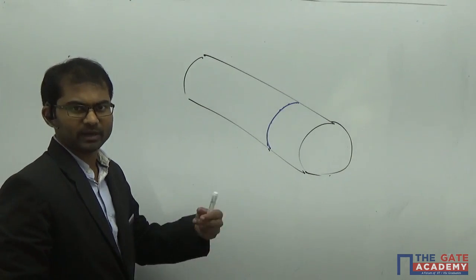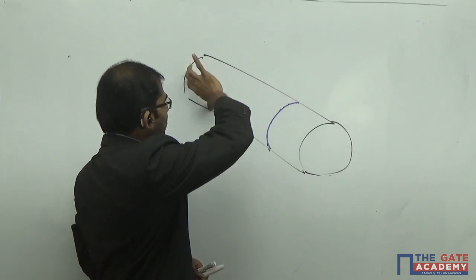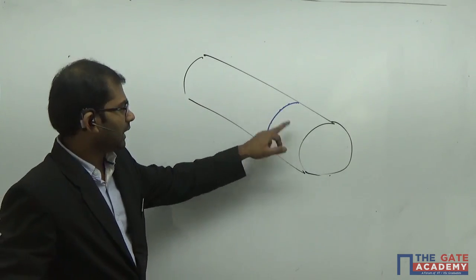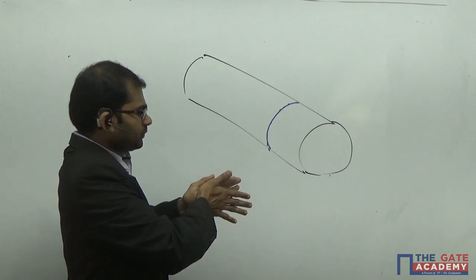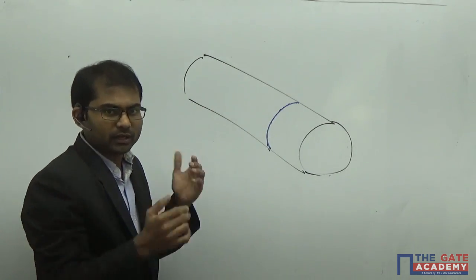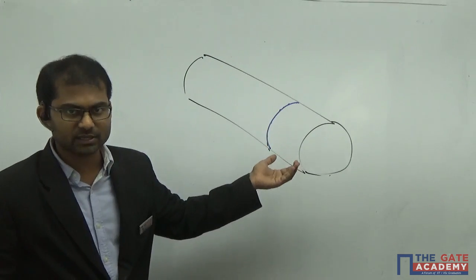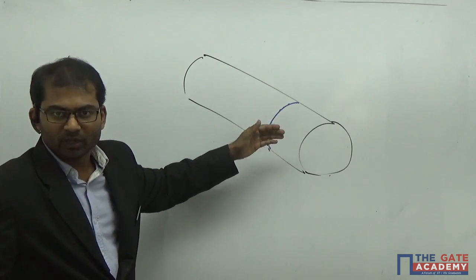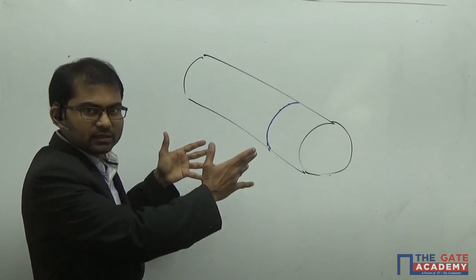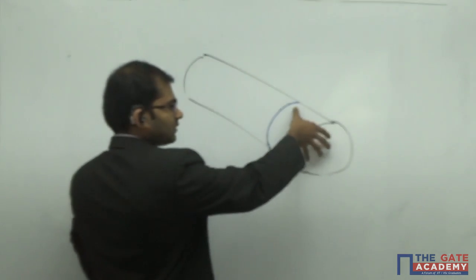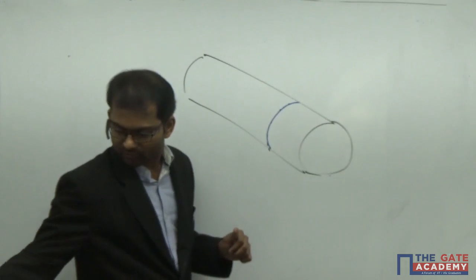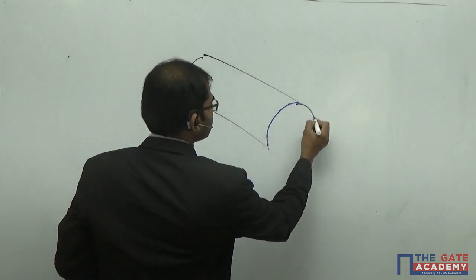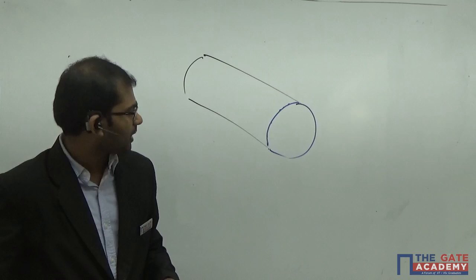When I apply torsion here, one part is twisted in the anti-clockwise sense and the other in the clockwise sense. If you consider the two members independently, we see there is contact occurring between them. In other words, take the shaft, cut it into two pieces, and join them back together. When I apply a torsion like this, one part actually slides over the other. Understand? So if you take the free body diagram for both of them, you get it in this way, after slicing off like this.